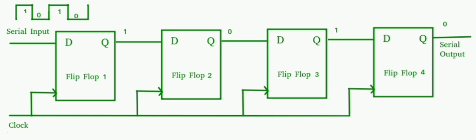State diagram. A state diagram represents a state machine and contains circles. They represent machine states labeled with a binary encoded number. Directed arcs represent transitions between states, labeled with input or output for the state transition.